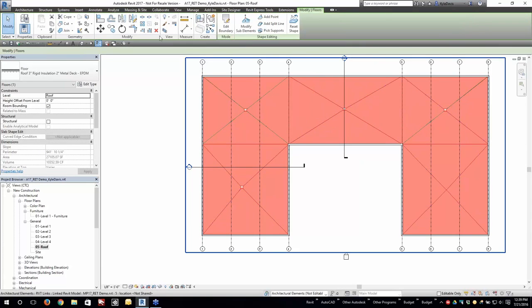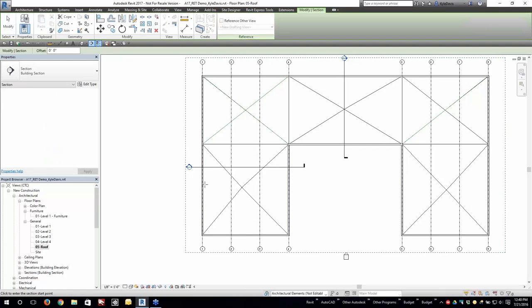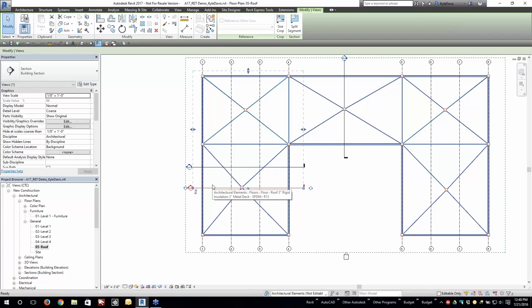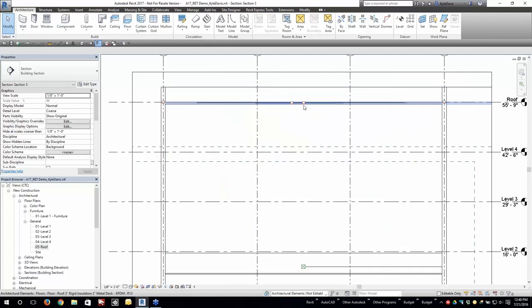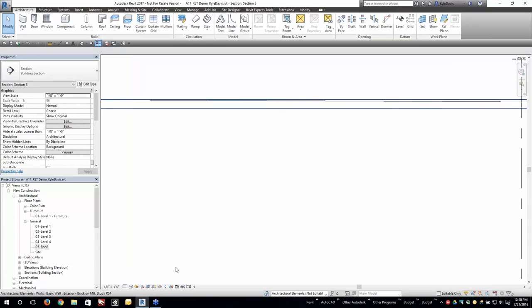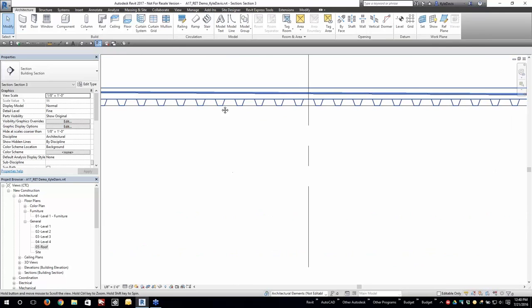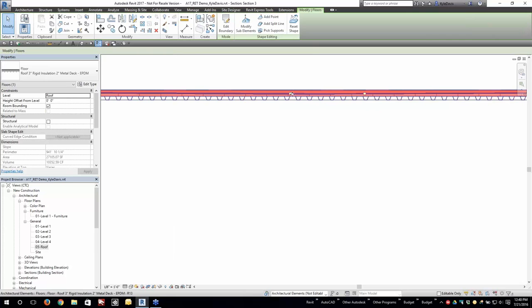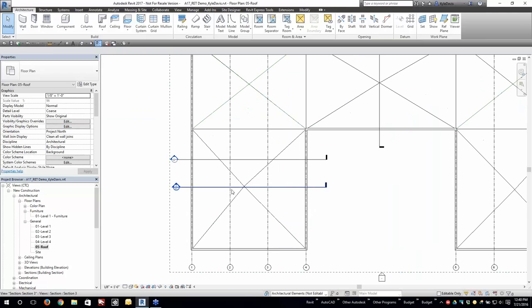And then in doing this, come back later, I'm going to draw a section here right through the middle of where that taper is, and then go to the section view, zoom in here, and you can actually see the top of this roof is starting to slope here. I'm going to go into fine level of detail and show that, in fact, the insulation is tapering to the point. So right there is a point. I can zoom in and actually see some of the lines there. Get a better look at this.